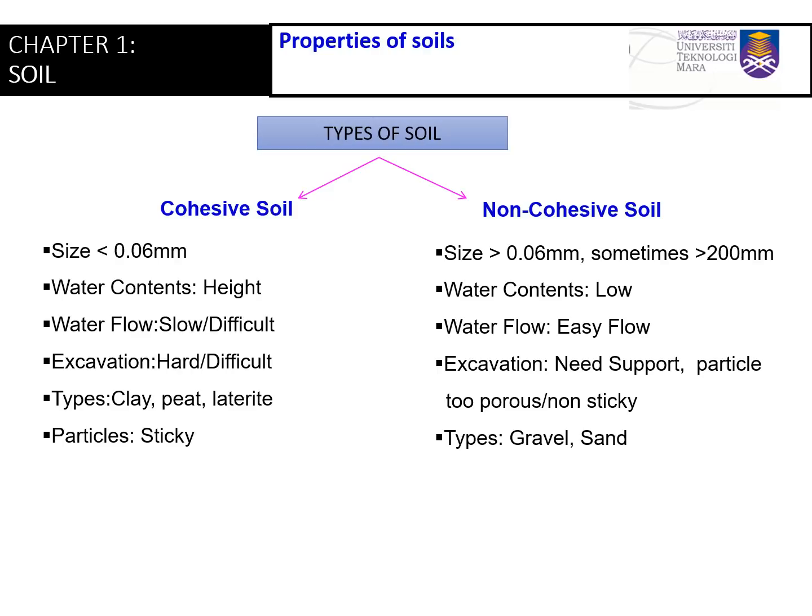But when you excavate, you need support. It's different from cohesive soil, which can hold its particles to each other, but non-cohesive soil is not holding to each other, so you need support, macam papan, something, so that the rest of the soil wouldn't slide into the excavation area.